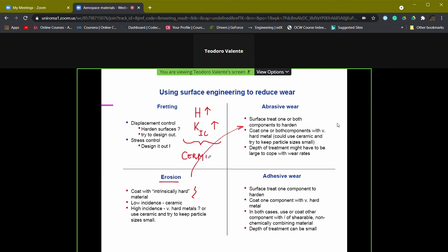That is, materials which have a metallic phase and also a ceramic phase. One important example we have mentioned, to be applied with HVOF, that is high velocity oxygen fuel spraying-based technology, if you remember, was tungsten carbide cobalt.